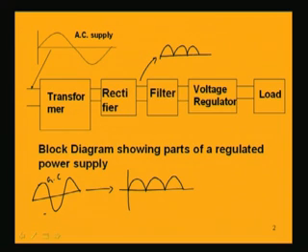So, what is done here, as we have earlier discussed, we use a filter circuit having a resistor capacitor. From this filter circuit we get the output as a voltage which is having this type of form. That means it is having ripples, no doubt, but it is in a better form than this pulsating DC.